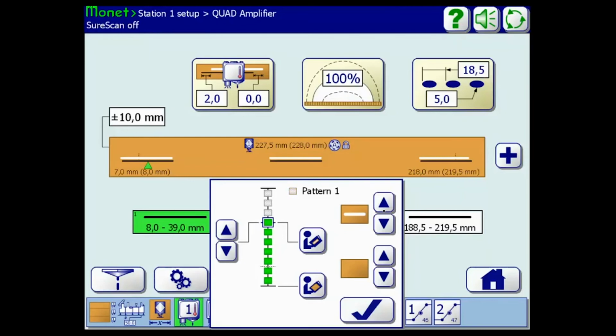Now your cap probably has an oval or rectangular, oblong opening at the bottom of it. Ideally, you will have that set up perpendicular to the product travel or the glue travel. And I would expect that all the sensors should be set up pretty much the same.